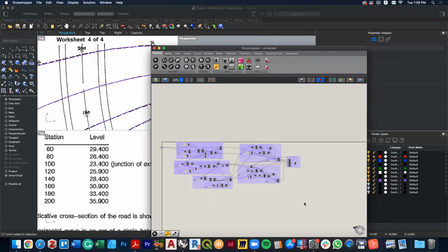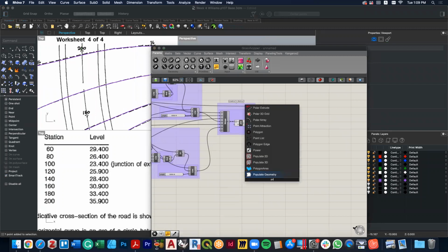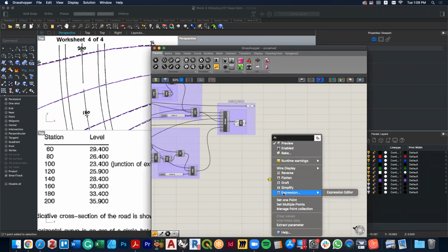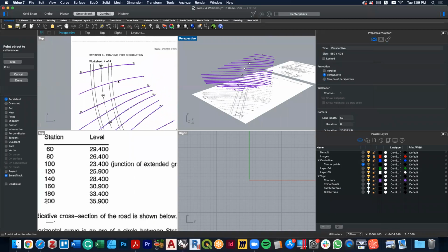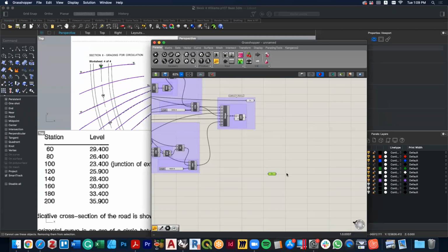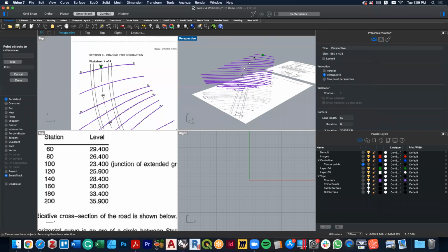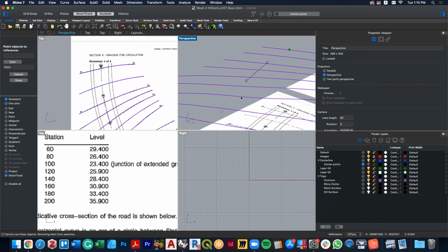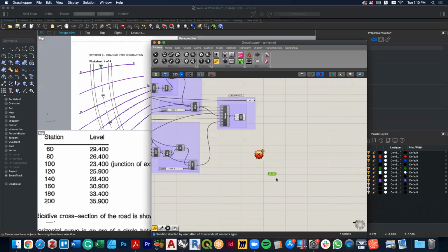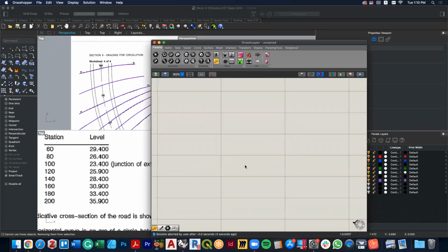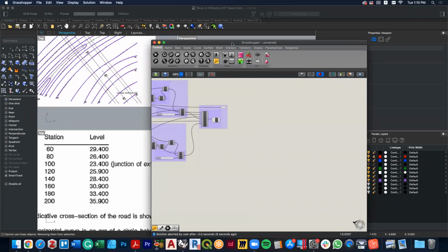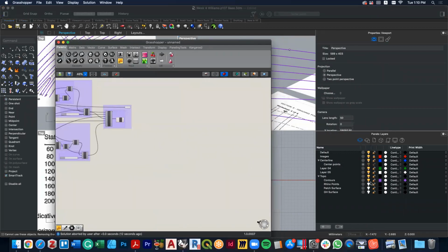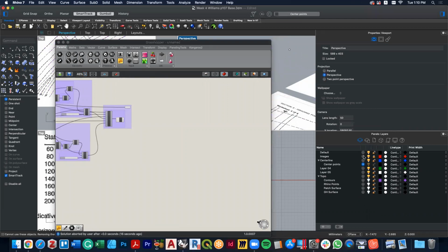So what I'm going to do is make the curve actually in Grasshopper. So if I go to point and then right click, set multiple points, then I can really just make my way through. Oops. I've done that in the wrong order. It's always worth remembering that you need to set the order of things extremely carefully. So let me turn off some stuff so that I'm not confusing what I'm doing. I've already locked the images.